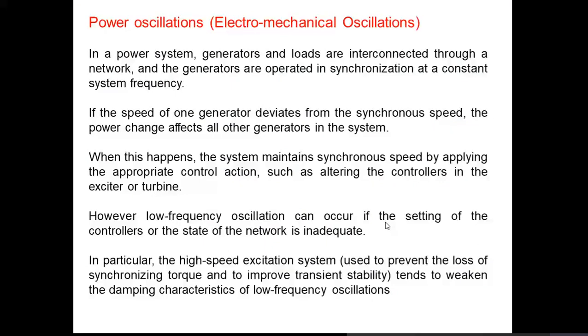On this slide, as you can see, normally when we have a power system, you have several generators, right? Some of smaller size, some of larger size in terms of capacity. Some generators will be driven by hydro turbine, and thus you may have salient pole generators. Some will be driven by steam turbine, either coal-based or nuclear power plants, and thus they have cylindrical shape generators.